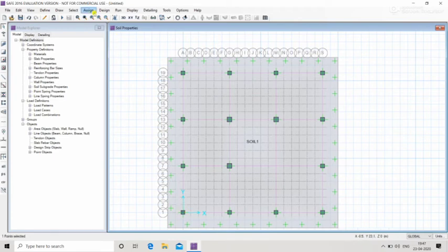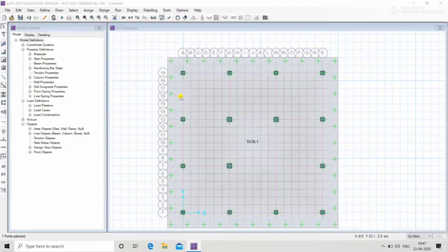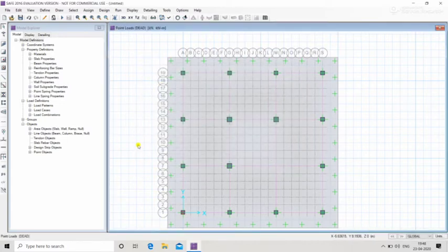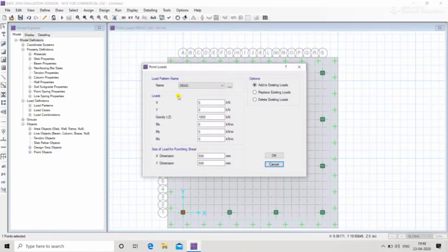For that, change the width from left right as 4 meter each. Then change the strip layer into A. Then we are going to draw the strip in layer A. The same way we are drawing the design strip in B layer also, so that you must change the option strip layer into B and then draw all the design strips.